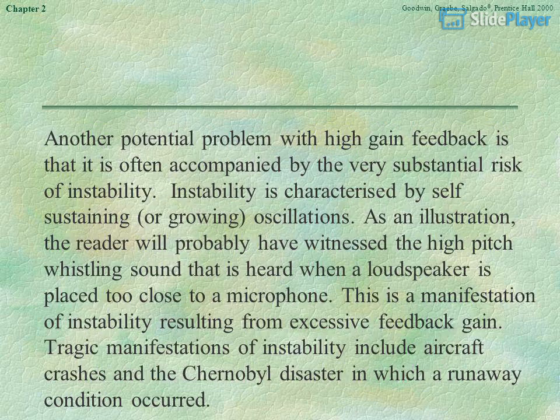2.8. Another potential problem with high-gain feedback is that it is often accompanied by the very substantial risk of instability. Instability is characterized by self-sustaining, or growing, oscillations. As an illustration, the reader will probably have witnessed the high-pitched whistling sound that is heard when a loudspeaker is placed too close to a microphone. This is a manifestation of instability resulting from excessive feedback gain. Tragic manifestations of instability include aircraft crashes and the Chernobyl disaster, in which a runaway condition occurred.